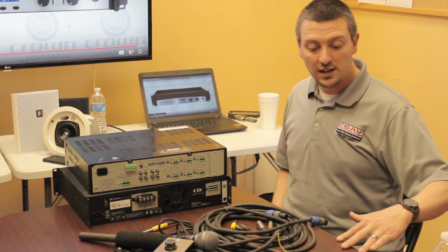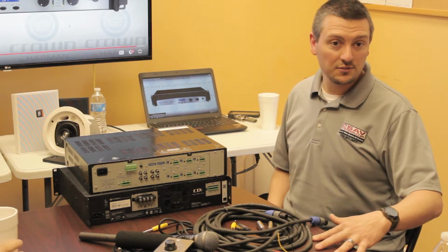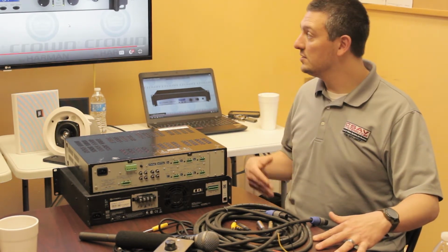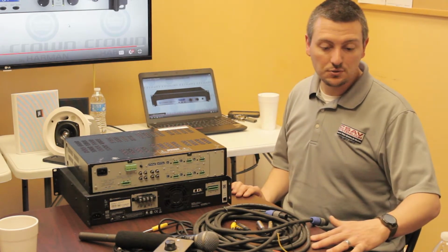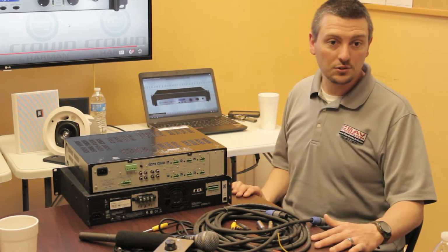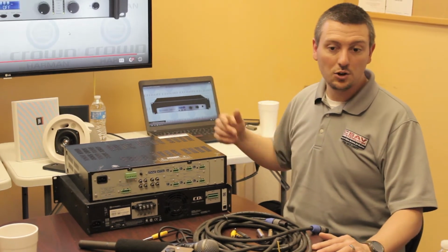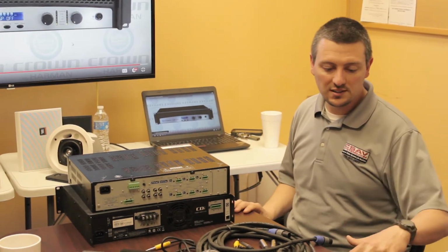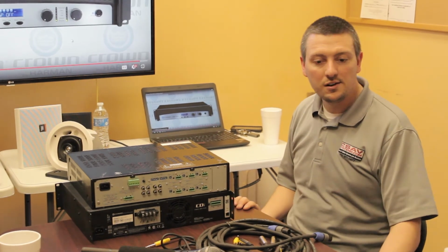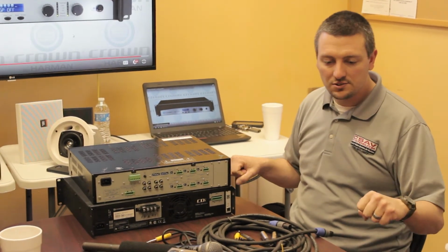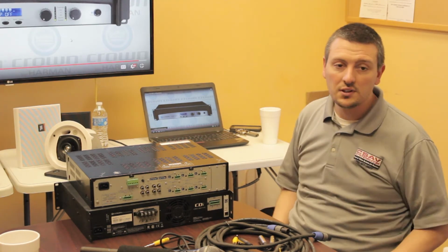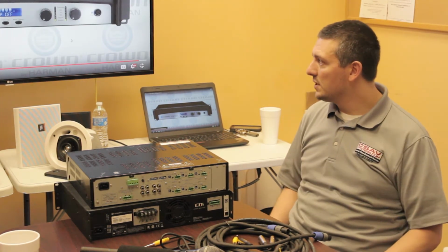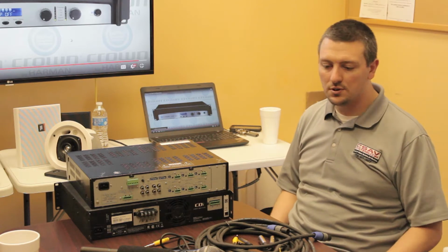You've got eight wires in a Cat 5 jack, but say to a balun, like a VGA balun, you're only using 6, not all 8, so you're passing video, but you might not be passing audio because that's on that last pair of wires. Without a tester, you're not going to know if something's shorted or reversed unless you really look at it. So having the right tools in that regard is essential.